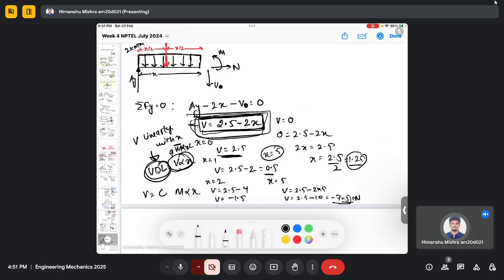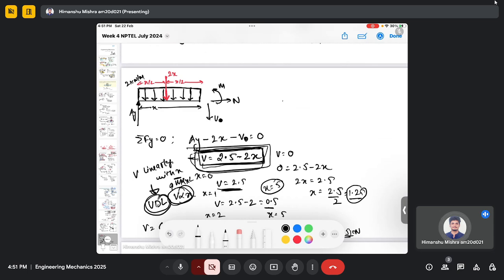Yeah, here you actually need to do it by inspection, but for the bending moment, you can differentiate whatever expression you get. You will differentiate that expression and equate it to zero, because let's say if your bending moment has this kind of a shape, when you differentiate and equate it to zero, basically you are saying that the slope here is zero.